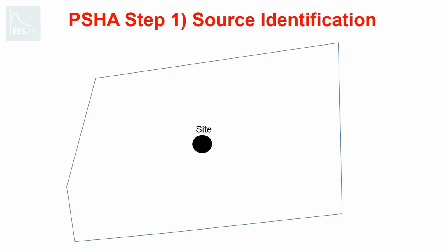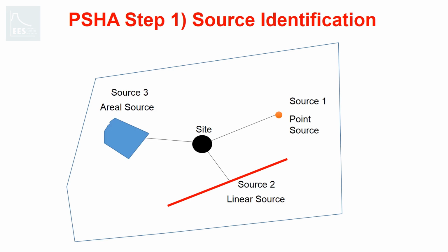So let's say you are given a location to estimate seismic hazard. At first you identify the probable sources that can create seismic activities. For calculation purposes, these can be represented by means of a point, line, or an area. If it is a point, then we call it a point source, line source, and for area, an areal source. However, keep in mind that this goes beyond the simple representation in the real industry. Engineering seismologists who conduct PSHA can model the entire 3-dimensional fault based on its tectonics and geological structure.